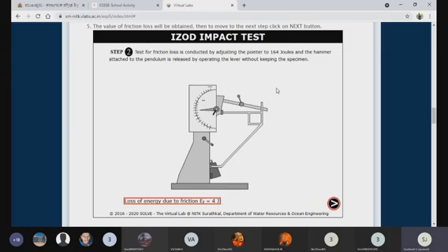The first step is to select the workpiece, then move towards the machine. In accordance with the experiment, if it is the Izod test, then raise the pendulum to 90 degrees. Then release it without the specimen and note down the residual values. Then you can place the sample. In the Izod test, the sample will be placed vertically in the machine. 50 mm will be inside the machine and only 25% will be outside the machine. The notch directly faces opposite to the striker face.